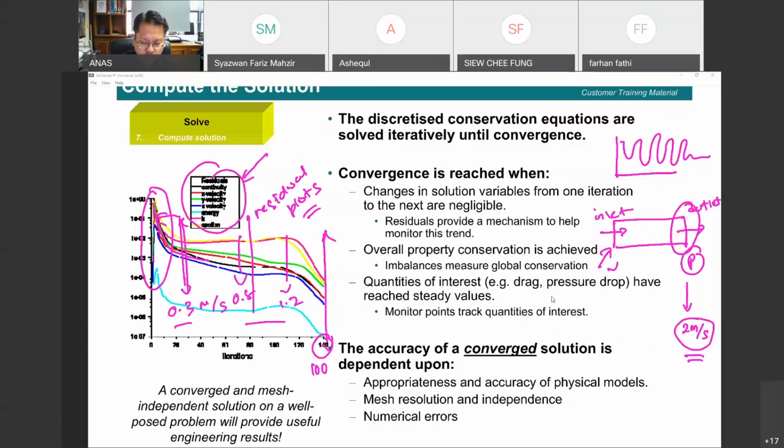If you set the value to be too low, let's say 50 iterations, and the equation hasn't been solved or the simulation hasn't reached equilibrium or convergence, then you are going to produce error. Basically, you get an output, you get a contour plot, yes, but your plot is not accurate. So the number here is actually subjective. It depends on your experience. Usually, for a simple problem, for FYP level, they just use a number between 200 to 400, or maybe 300 to 500.